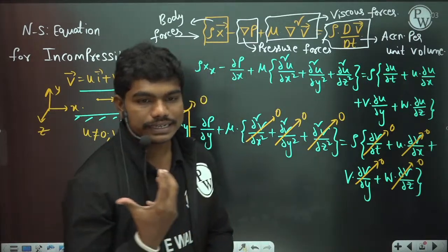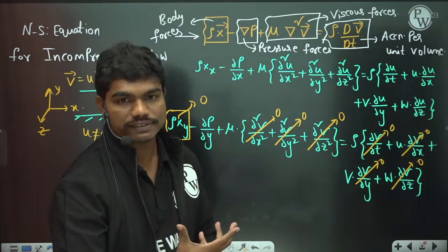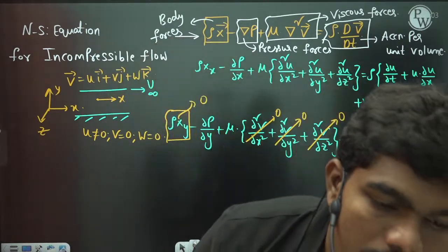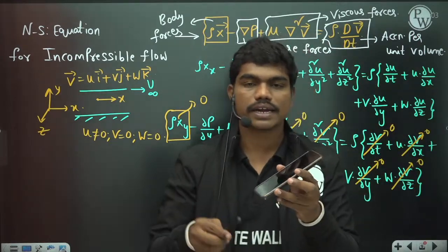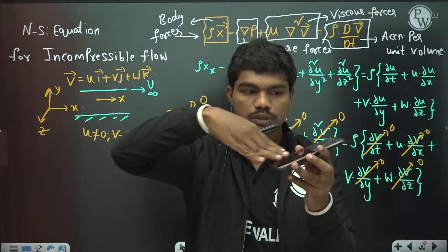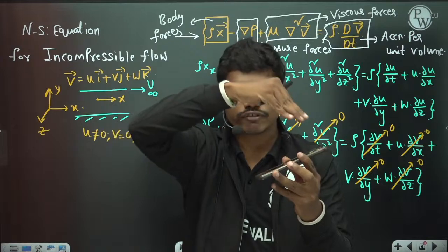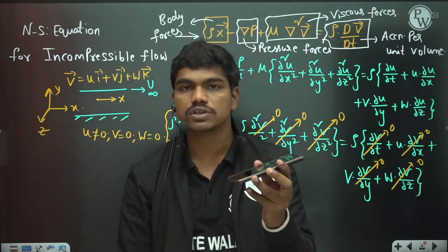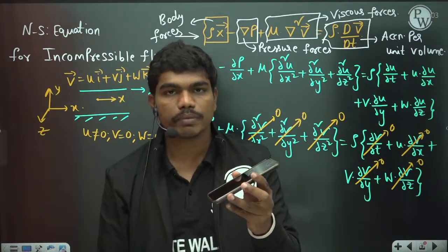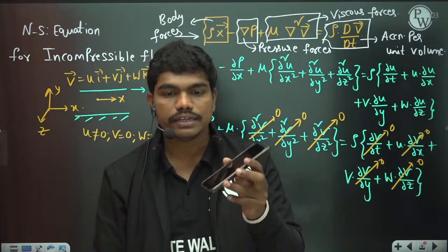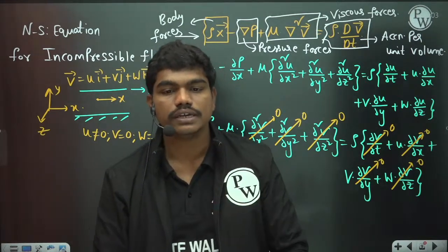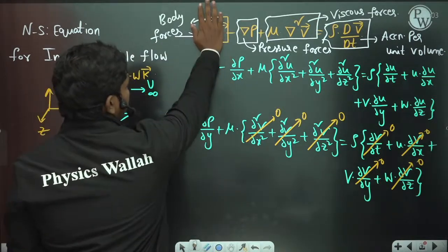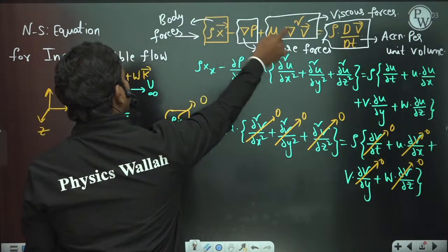Generally, in these kinds of flows we call them pressure driven flows. But suppose I take an inclined plate like this, and I put some fluid on it, then the fluid flows because of gravitation, rather than pressure forces. So when fluid flows because of the gravitational force, these flows are called gravity driven flows. So when pressure driven flows are there, we neglect the effect of body forces.